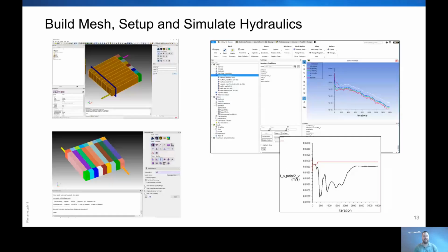So then the mesh is built from the geometry, and the top left shows the process of decomposing it. The mesh needs to be well defined in different areas to make sure that you have a quality mesh, and so the overall fluid volume will often be cut up, or individual surfaces or faces may have mesh parameters assigned to them to control their size.